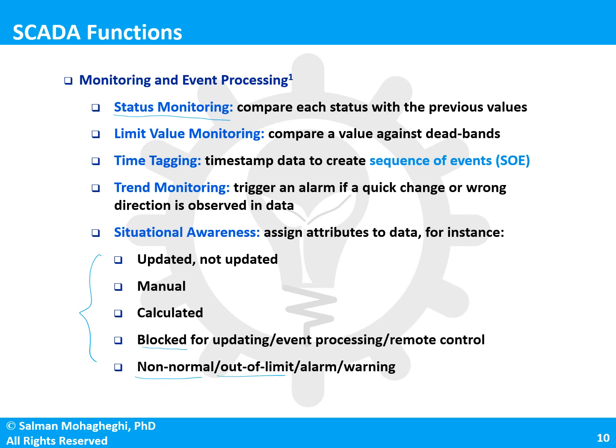Imagine you have been measuring a particular node voltage for weeks and weeks, and all of a sudden you measure a value that is not close to what you have been measuring in the past. Now this value may not necessarily be wrong. For example, you may measure a voltage of 1.02 per unit. There's nothing wrong with this voltage.